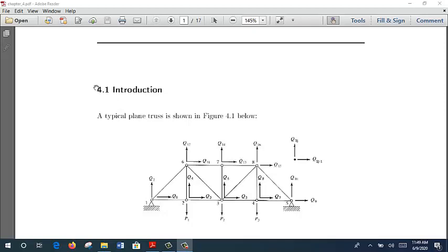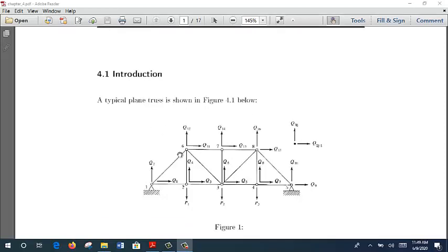secara analytical, secara calculation, we need to know the assumptions that we need to understand. The first one, the bar is geometrically straight. You can see from here the bar is geometrically straight. The second one, the material obeys Hooke's law, F equal to Kx. And the third one is forces are applied only at the end of the bar, not at the middle of the bar, for example.